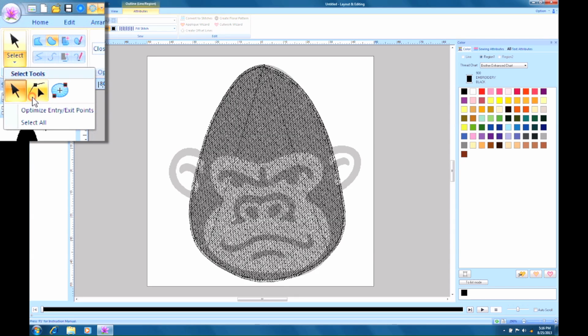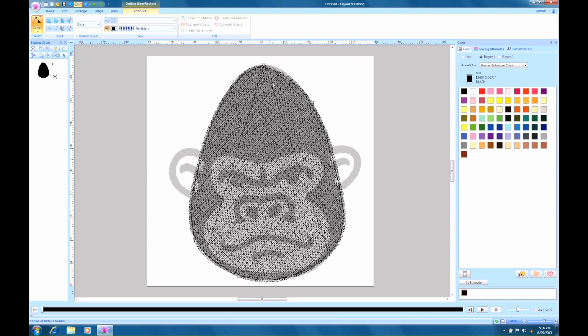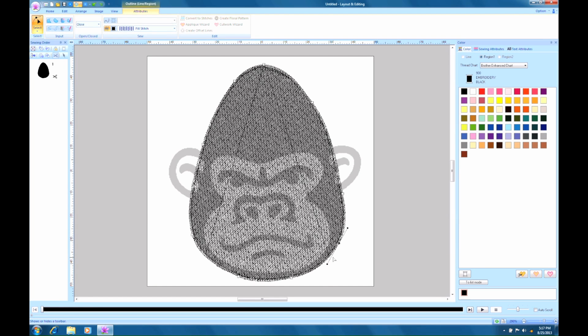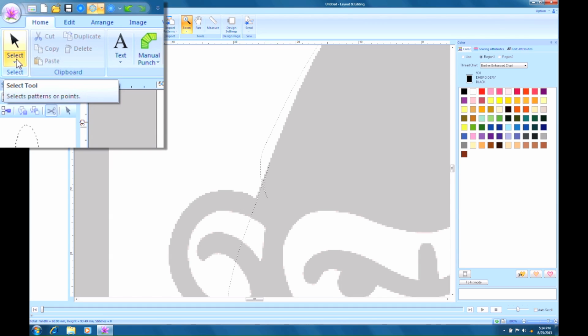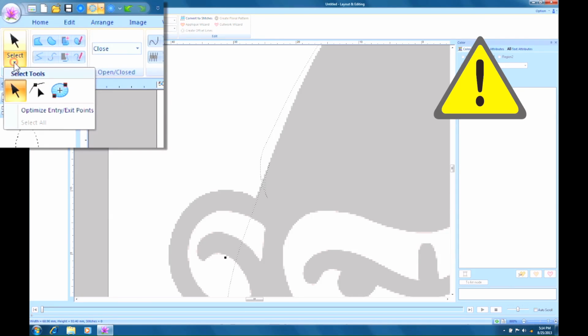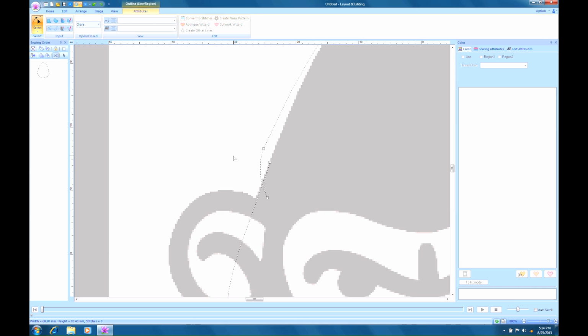You can adjust the points to improve the quality of your data. When the region sewing settings are applied, you're ready to move on to the next step. If the region sewing settings are not applied, you probably have overlapped points or crossed lines. Use the Point Edit tool to adjust the problematic portions.